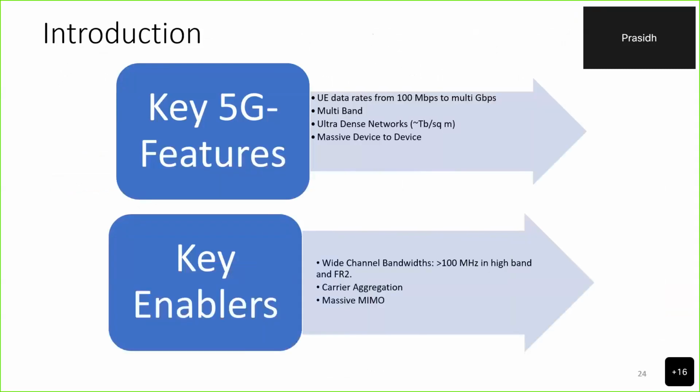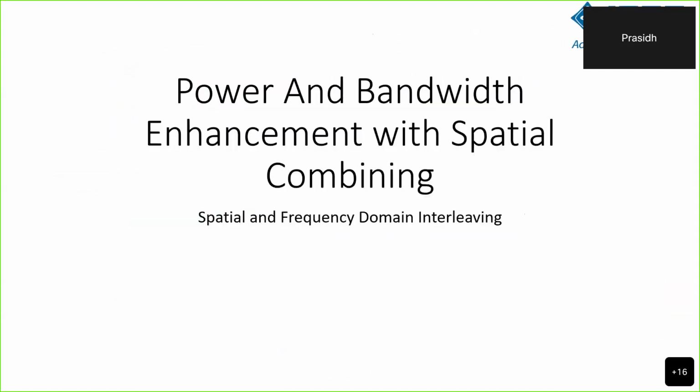Now, until now, we were only looking at combining power spatially. Now the thing is, we are not going to operate with CW signals, I mean, say unmodulated signals, unless one is actually working on things like accelerators. Or one is also not going to operate with just constant envelope modulated signals, like QPSK or 8PSK, unless one is actually doing satellite communication.